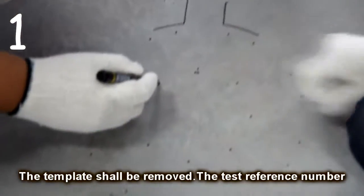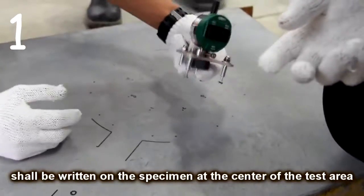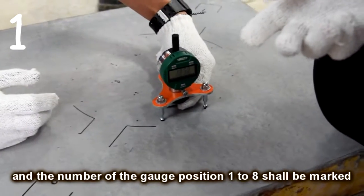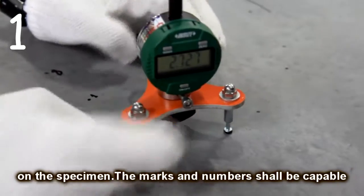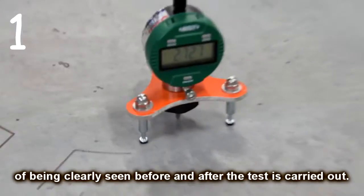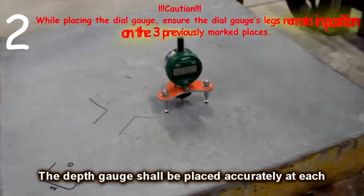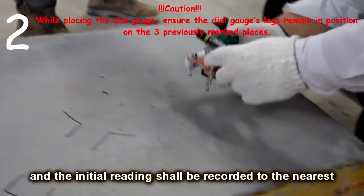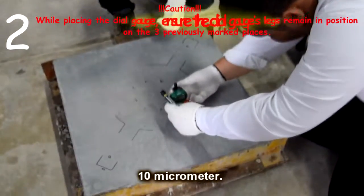The test reference number shall be written on the specimen at the center of the test area, and the number of the gate position 1 to 8 shall be marked on the specimen. The marks and numbers shall be capable of being clearly seen before and after the test is carried out. The depth gauge shall be placed accurately at each of the 8 measuring positions on the specimen, and the initial reading shall be recorded to the nearest 10 micrometer.